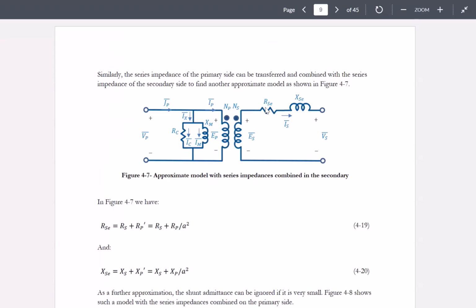So there would be no voltage drop in this path. Whatever you measure would be associated with this path. Now you can apply the rated voltage on the primary because you're not shorted now. You are open on the secondary. So apply the primary nominal voltage on the primary and get that current measured as well as the power measured.